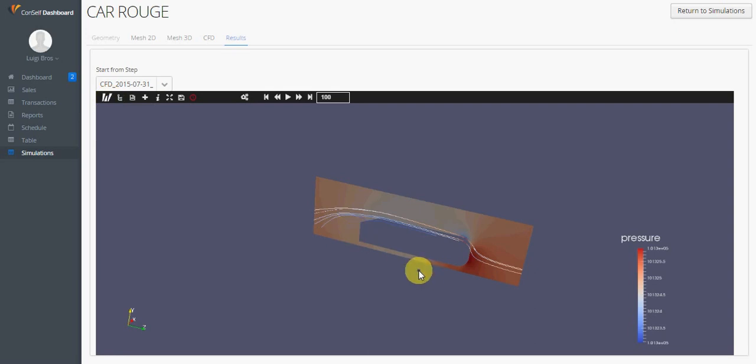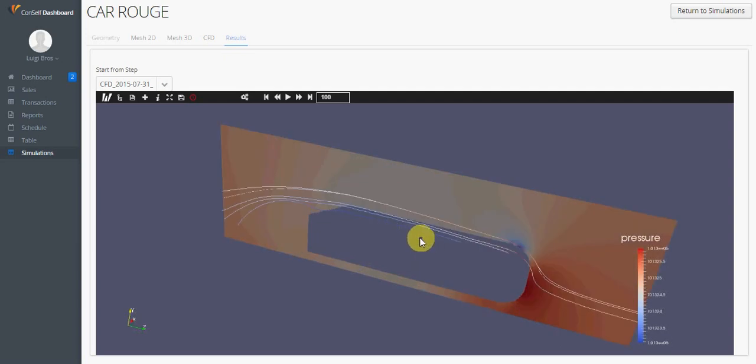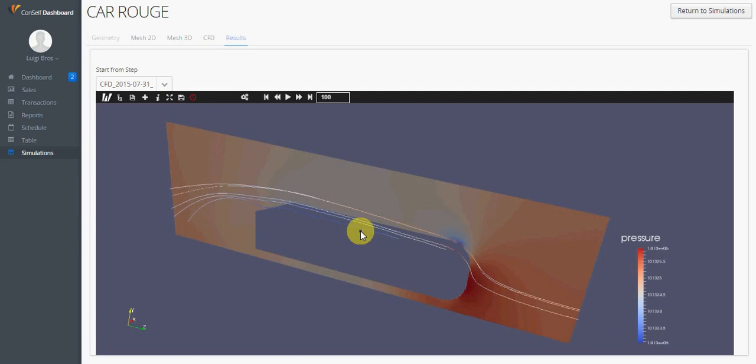In order to zoom in, you have to click with the right button of your mouse and drag down a little bit. The scene automatically zooms in towards the simulation. And with the middle button, the central button of your mouse, you can move the slice across the screen.